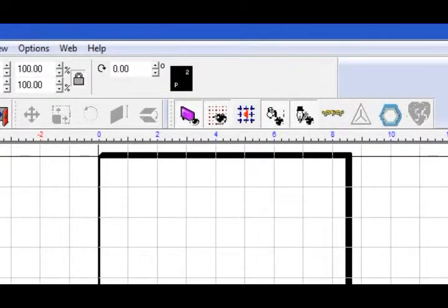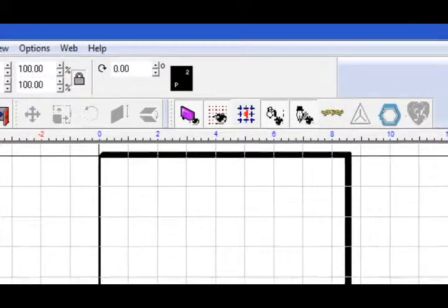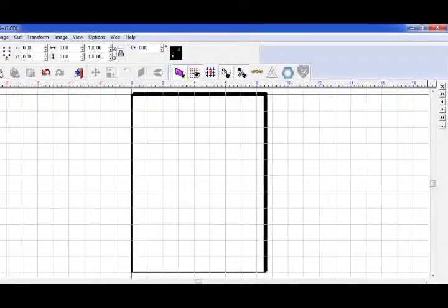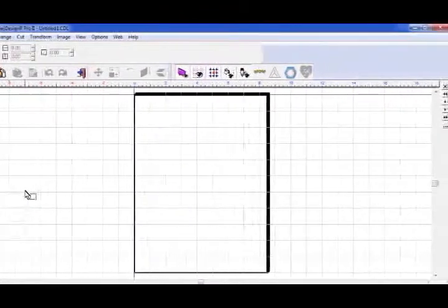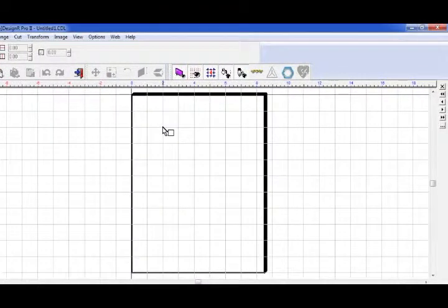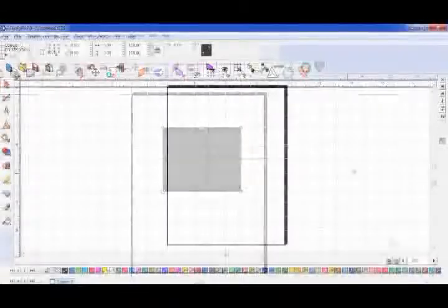It will enable Snap to Grid. Snap to Grid will ensure that anytime we click on the workspace to manipulate or create an object, it will automatically snap each point to the nearest grid point. To briefly demonstrate this, let's enable the Snap to Grid and then draw a rectangle. And as you'll notice, as we start to draw the rectangle, they're automatically snapping to the grid points.